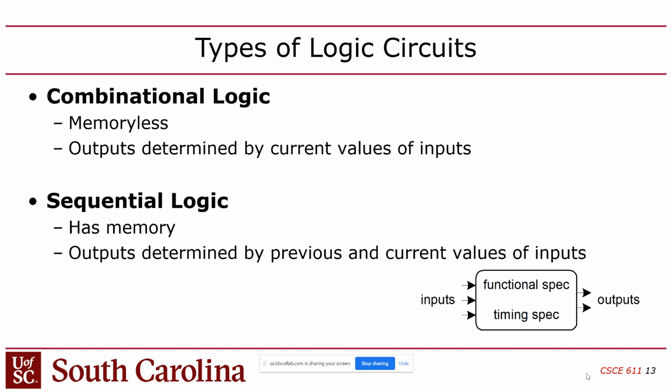Depending on which idioms you use inside, that defines what it is. And you can mix them together too. You guys with me? You can have one module that has some combinational logic and some sequential logic in it, as well as some structural HDL, which is just an arrangement of connected modules, and some behavioral HDL, which could be essentially some Boolean logic.